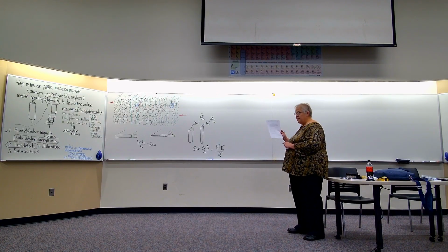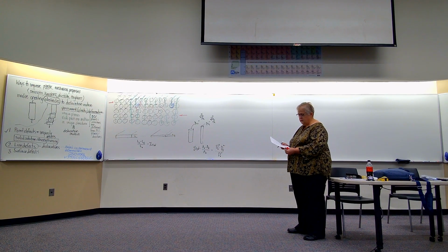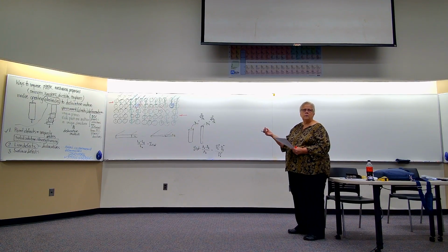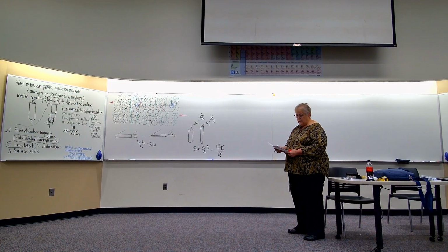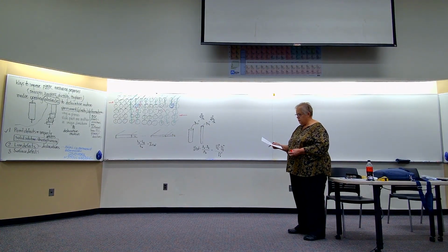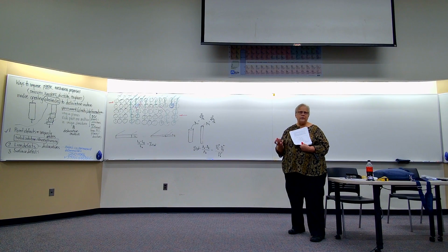If you look at the image on the left, you have percent cold work, and how that's measured depends on the geometry of the part, and you have the resulting yield strength. Steel is unique in that you can get a lot of strength increase up to a point, and then there's not much more. Whereas with brass and copper, there's a continual increase with percent cold work. In all cases, the picture on the right tells you the cost involved with doing this.